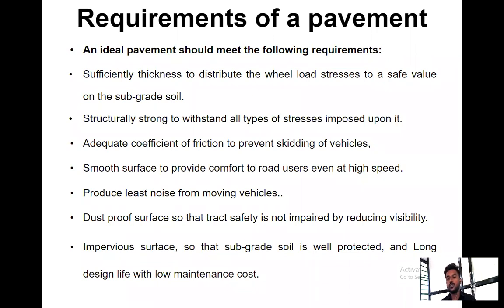Impervious surface, so that the subgrade soil is well protected, with a long design life and low maintenance cost. The surface should be impervious, as well as given a slight slope, so that whenever water is there, it will be removed and flow out to the channels. If there is no accumulation of water, there will not be any chances of hazard on the road.